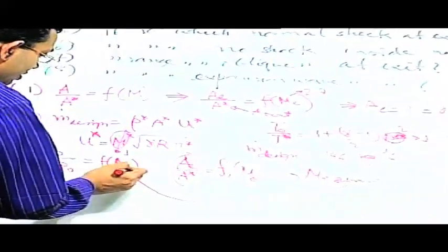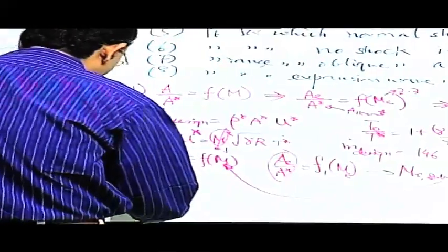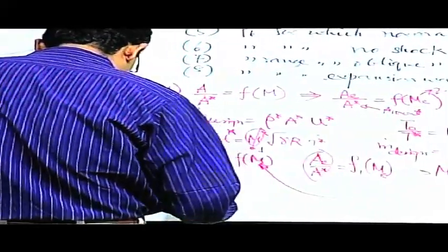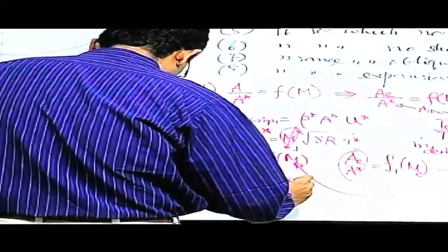So, once you get that one, you may plug it back here to get P as a function of P0. So, that P will be the lowest back pressure for which the subsonic flow exists throughout the nozzle. So, we can find this to be equal to, that is the pressure at this point C, 780.5 kilopascal.